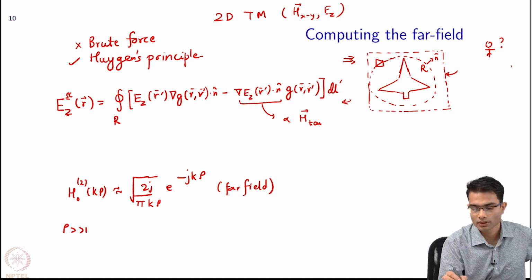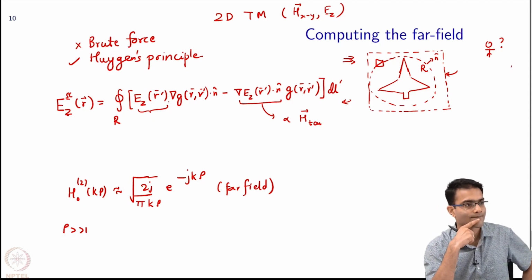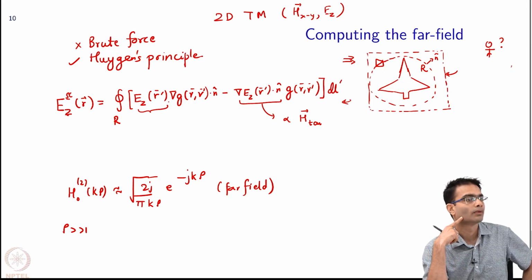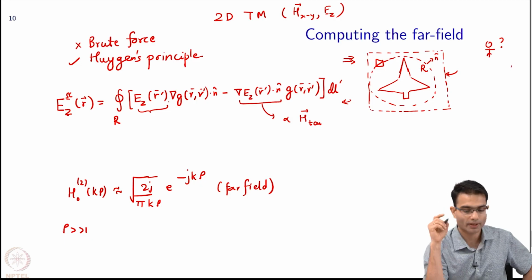So that's another nice part about the edge based FEM that I got this straight away. So I know this. What about this guy? Do I know this guy? I don't know it, but can I calculate it? How? Maxwell's equations, taking curl of H will give me E. How do I take curl of H now? I know H as numbers, not analytically, right?